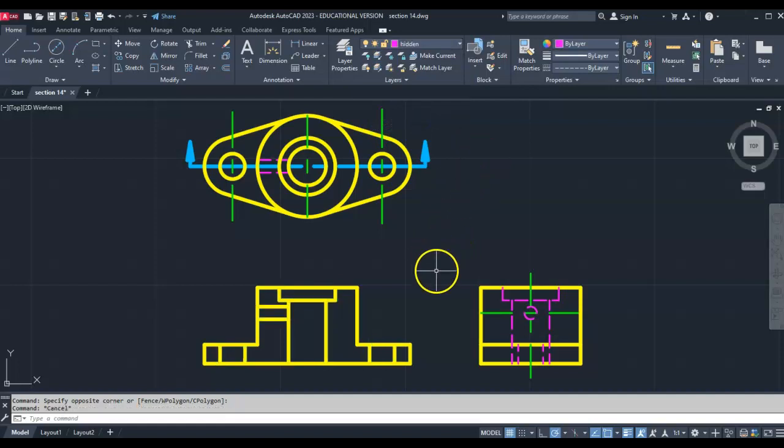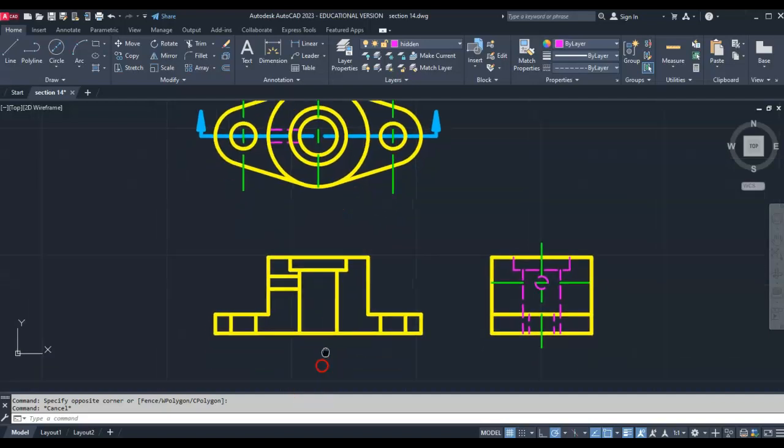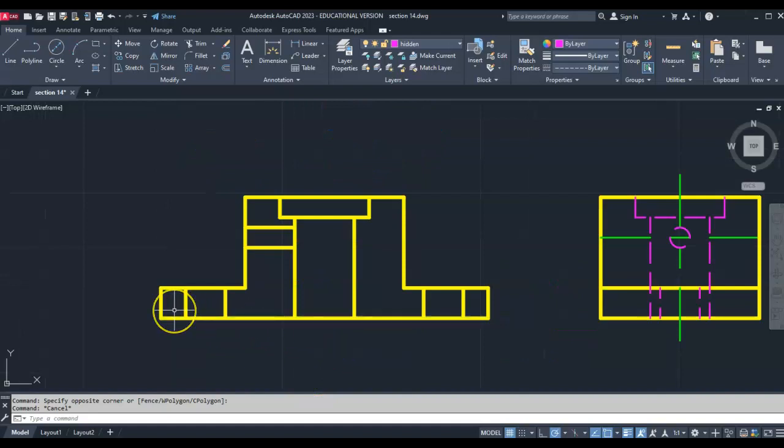Alright. In section views, if there are other hidden lines further back, so like this curve here, I could have a hidden line showing on the far side, the back side. In section views, you're only worrying about the surface where it's cutting through. So don't worry about hidden lines on the far away side. Now, if I was just looking at this view, this one's a relatively simple one, so it's not too bad. But I want to show where there's empty space and where it's solid and being cut through. So to show that,